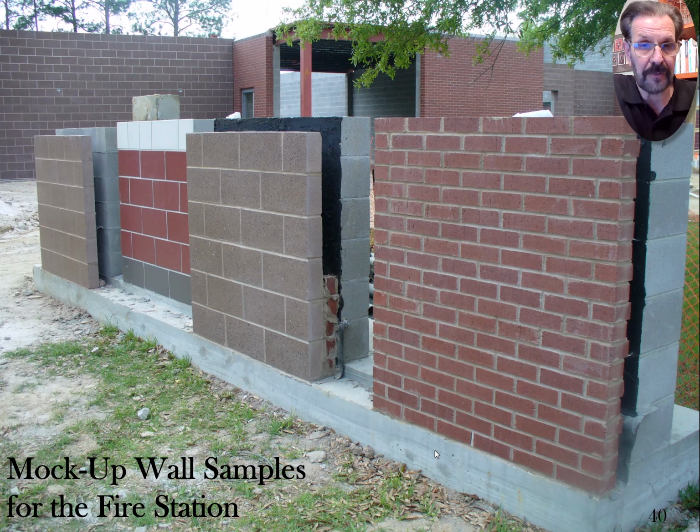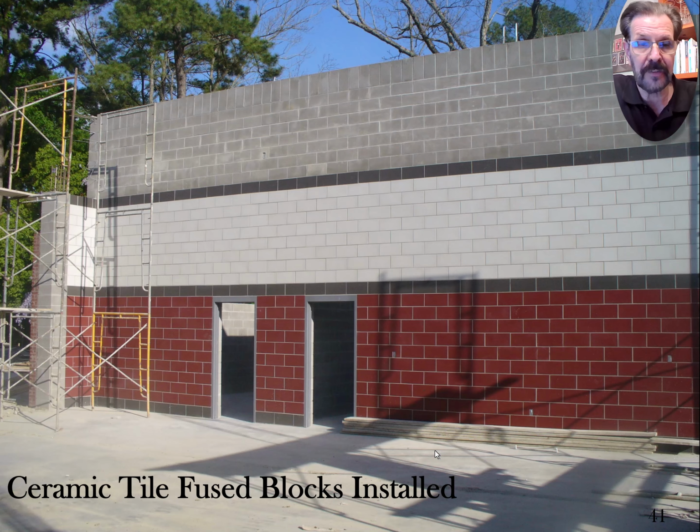So that ceramic tile is right here, and this is inside the garage bays where the fire trucks are parked. And you see right at the very, very top, we've got that tall bond beam installed, where you've got the 16-inch block standing upright with the deep bond beam. This is a 16-inch tall bond beam, basically.